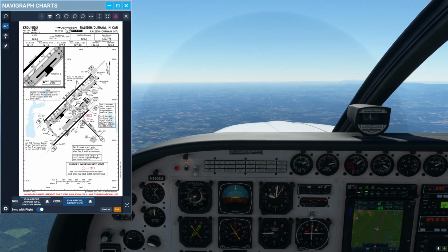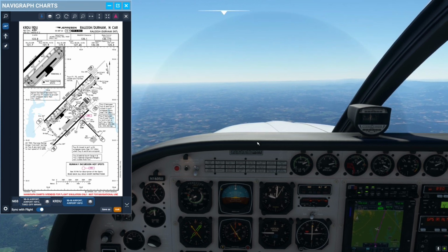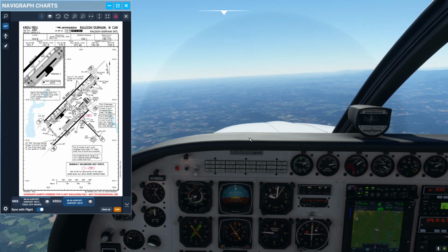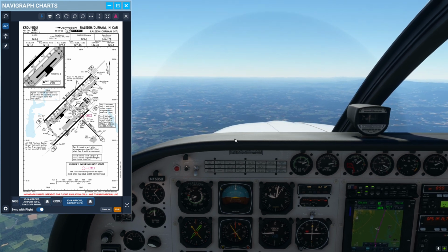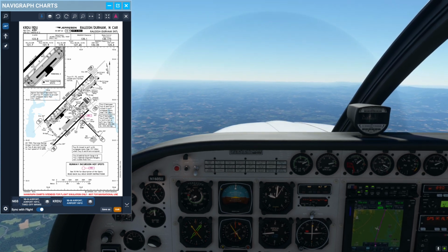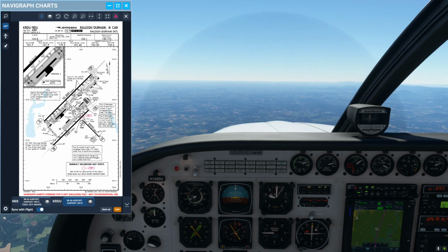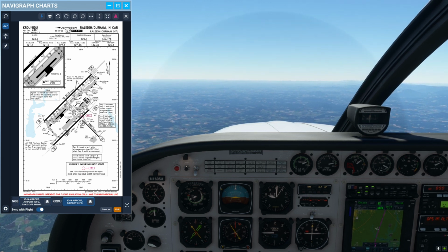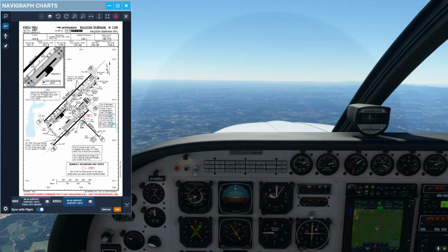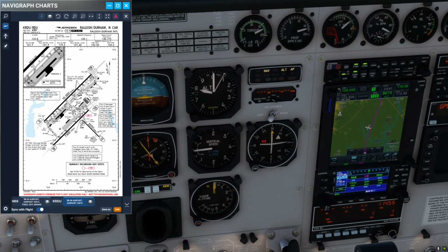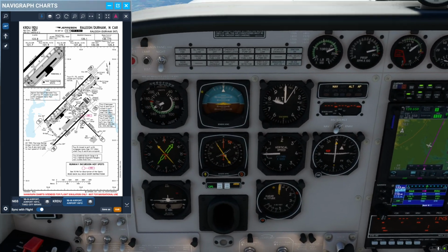If you know what the wind is, you have to figure a wind component so you don't get blown off the distance that you're trying to keep in the pattern. But yeah, always bug your runway headings. It could never hurt. The only place it could cause a problem is if you're actually flying a route and you're navigating by the heading setting on your autopilot. Well, then obviously you won't be able to bug the heading. Guess you could do it. I don't know how you do it.